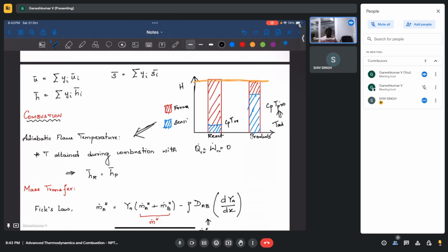It's not exactly like there will be a flame and the flame will have that temperature. Usually the flame may not reach adiabatic flame temperature. Ideally it should, but because of heat losses, and because the products, CO2 and H2O, at very high temperature will not remain as CO2 and H2O. They will decompose into CO, OH, H, O2, and NO can form, all of which requires some amount of energy.